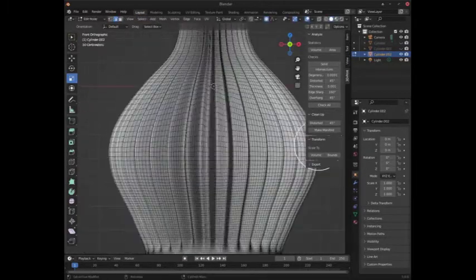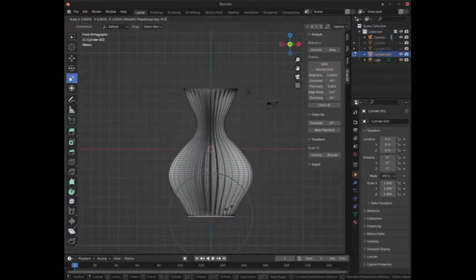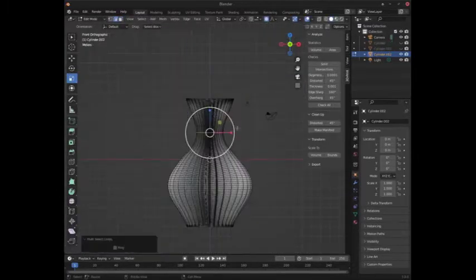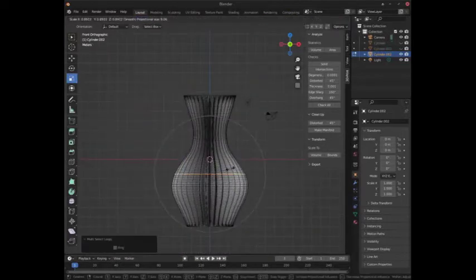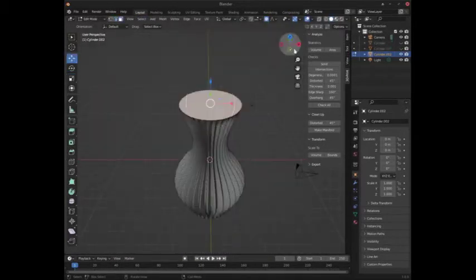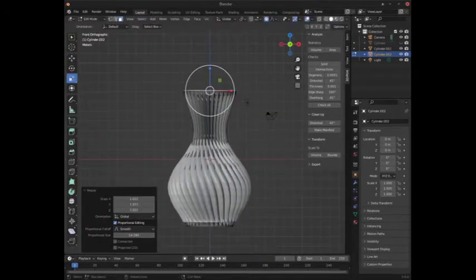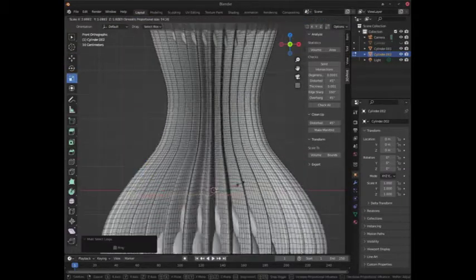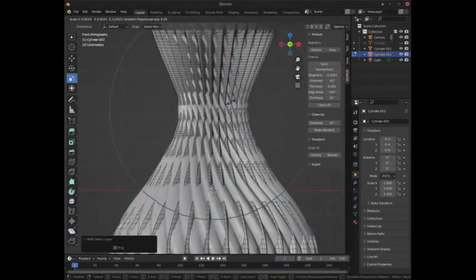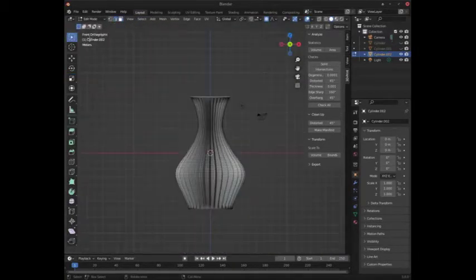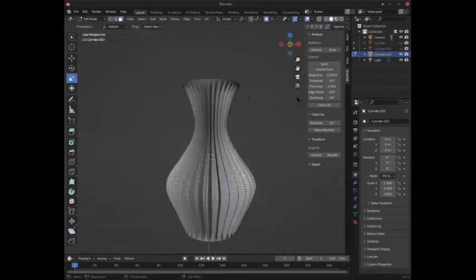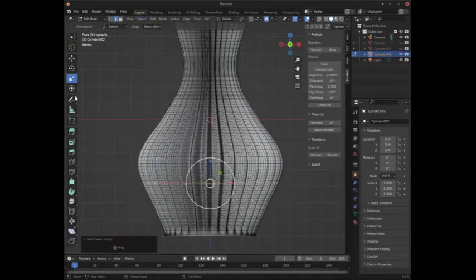In Blender, you need to consider meters as centimeters, because by default, Blender will display its units of measurement as just an M for meters, and you need to just keep in mind that those are actually centimeters when you export them. I think I got that wrong anyway. I'm not sure what I did. It ended up being smaller later on, you'll see.